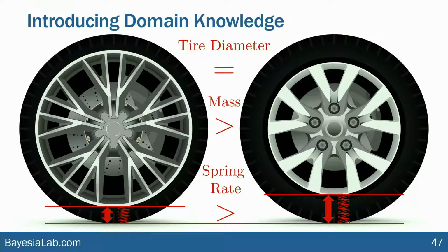Also, the bigger rim is a lot heavier than the smaller rim. And given the different sidewall height, inevitably the tire of the big rim on the left would have to have a much higher spring rate, and at the same time would also have a higher mass.